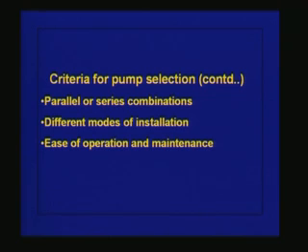That means we are operating these pumps in parallel, and that is also an important consideration in selection of the pump, particularly the number of pumps that we need to have, and what should be its size, and so on and so forth. In some cases, for the same discharge, the delivery point could be at a much higher level compared to the water level in the sump, or the lift is very high. In such a case, I can use a single pump which gives the required discharge as well as is able to lift the water to a much higher elevation, or I can use 3 or 4 more pumps in a series operation.